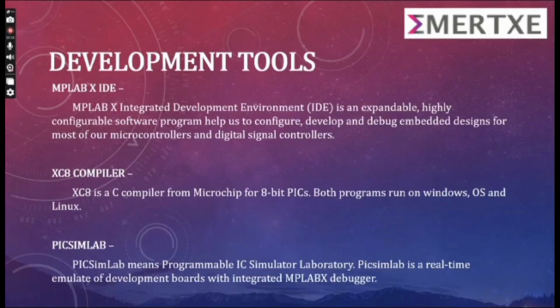The development tools that are required for this project are mentioned below. They are MPLAB X IDE, which is an integrated development environment, an expandable, highly configurable software program that helps us to configure, develop, and debug embedded designs for most of our microcontrollers and digital signal controllers. Next is the XC8 compiler. This is a C compiler for Microchip 8-bit PICs. Both programs run on Windows OS and Linux.